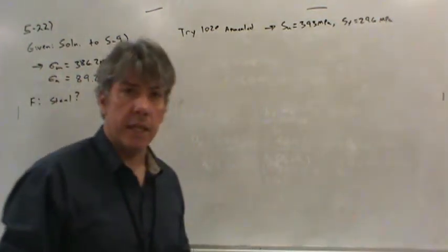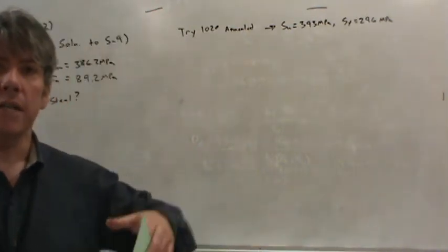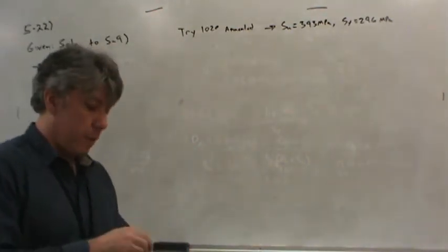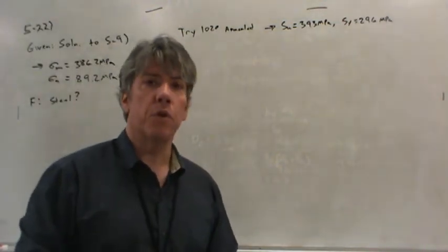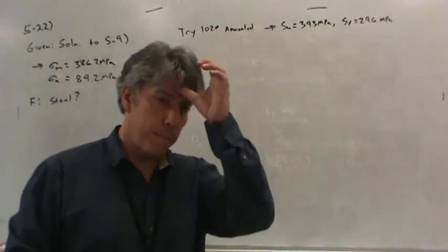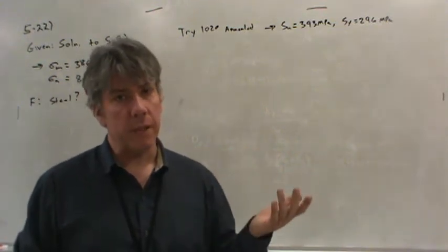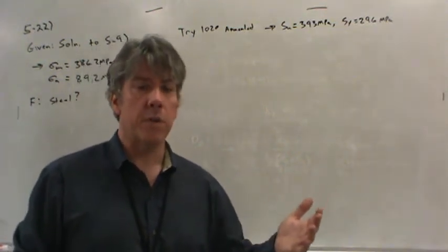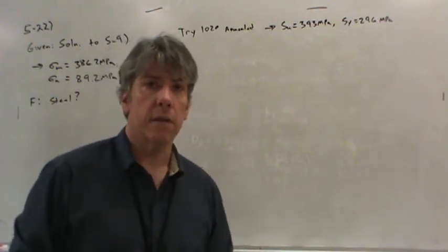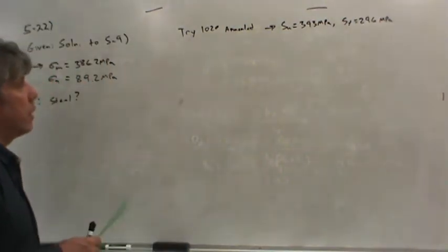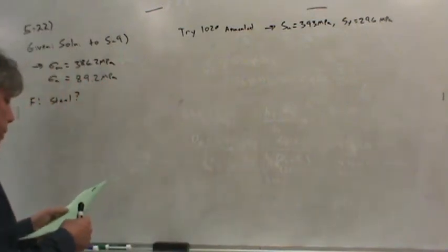Now it has a lot of ductility. I think the ductility was 35% or something ridiculous. So it could stretch like crazy, which was really good because remember this spring is deflected pretty far. Most of the time we assume that the beams that we're designing don't deflect very far, but this is deflecting by 0.4 millimeters and the span's only 40, so it's deflecting, what is that, a hundredth of its length? That's a pretty big deflection for what we're doing. And so I thought, well, let's get something that has the highest ductility I could find. And so this was the weakest, but it was also the highest ductility.